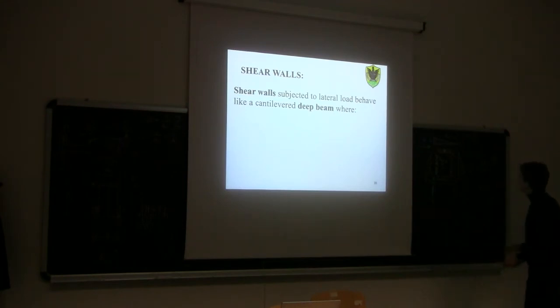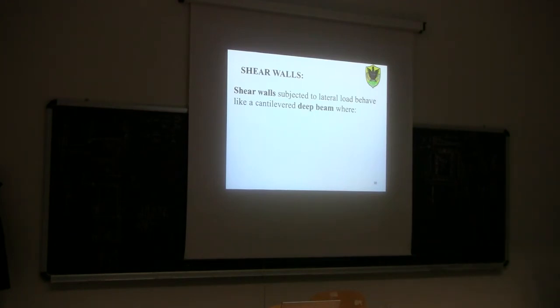So this one would be V times S, and V is the same. So in general, the shear force of one nail connecting the sheathing with the stud is given by V times S, so F over B times S. Okay? This way we can calculate the shear demand in a single nail.